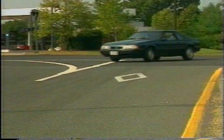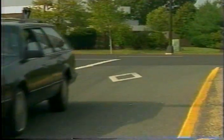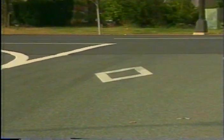Markings are white diamonds identifying HOV lanes. The diamonds are placed from 25 to 300 meters apart, depending on whether it is a city street or a freeway.